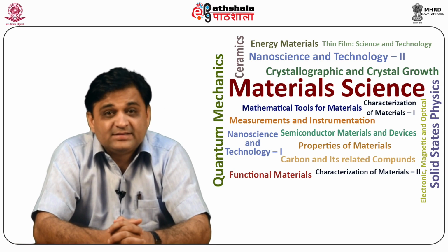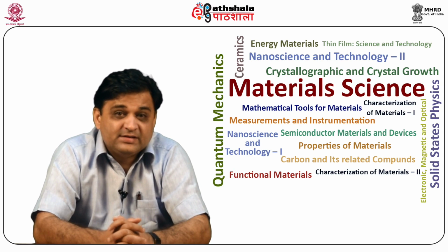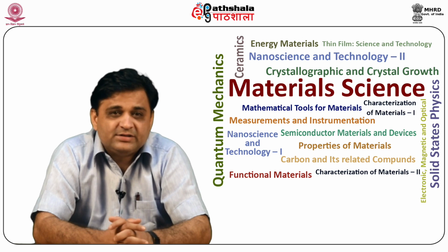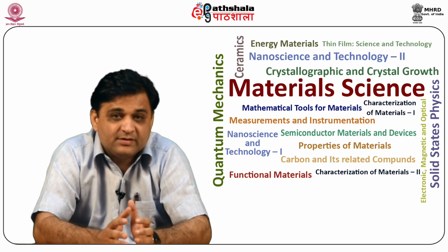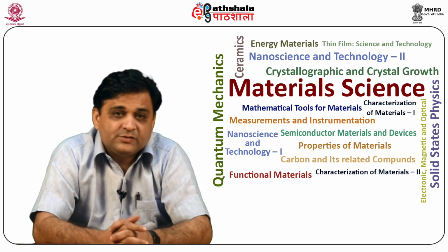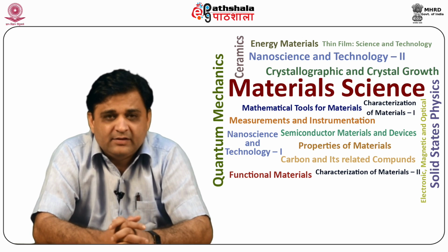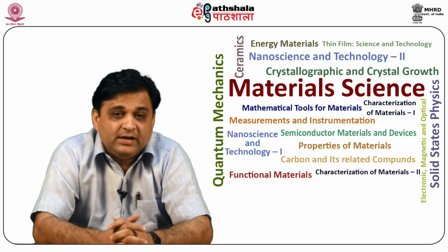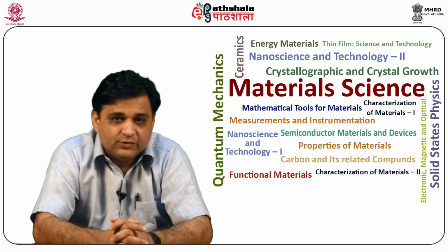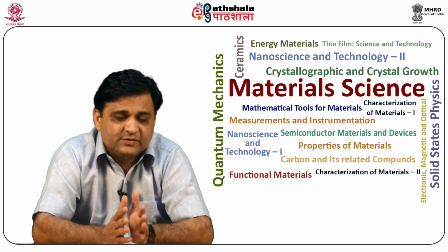So students, let us summarize what we have learned in this module. First, CVD is a technique used to synthesize ultra-thin films of semiconductors and metals on chosen substrates. CVD can also be used to grow nanostructures on solid surfaces, and on the other hand, in soft condensed matter, the Langmuir-Blodgett technique is used to grow monolayers of surfactant molecules, and different phases such as gas, liquid and solid can be identified using the surface pressure isotherms.